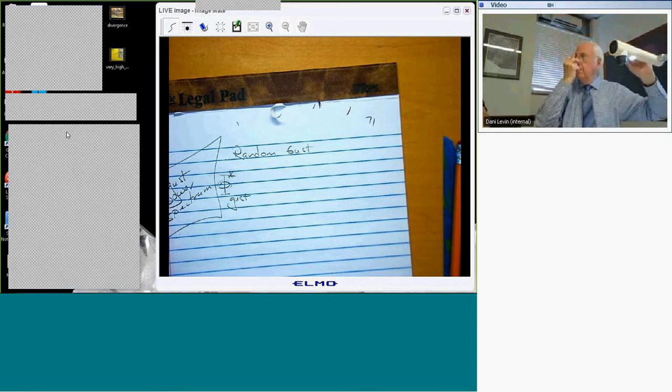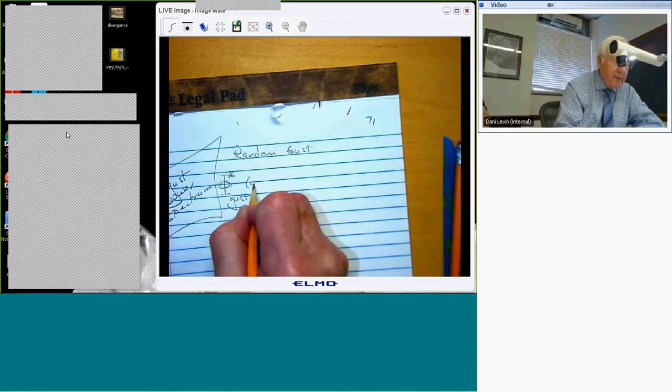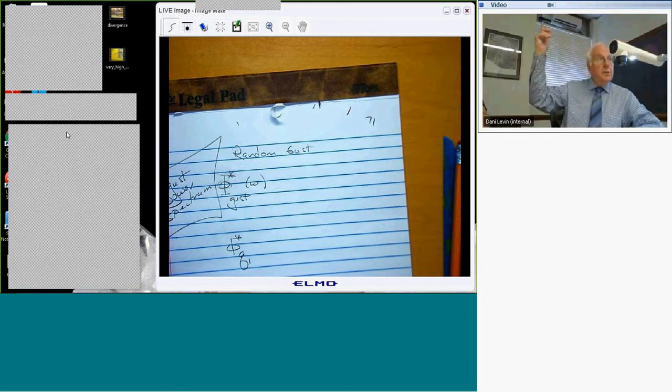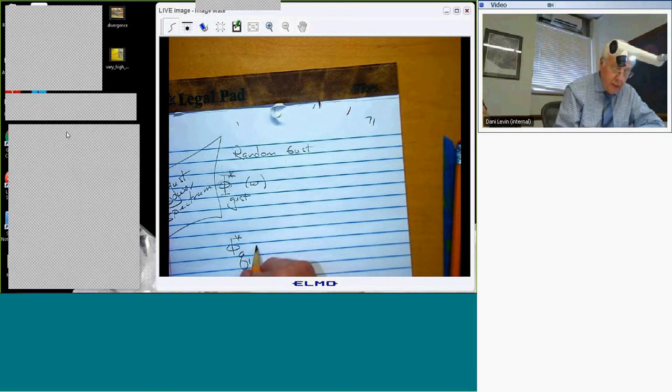If this is only a function of frequency and not a function of x and y, then if I want to find the power spectrum of, let's say, Q1, and since I only have one mode, that's equivalent to finding the power spectrum of the plate displacement, right? How do I write that in terms of the power spectrum of the gust?